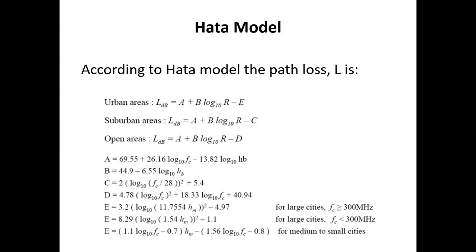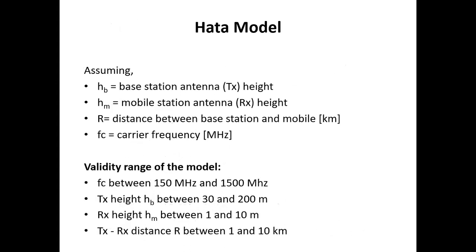But the maximum frequency was 1500 for the original Hata model, and it was found insufficient. I mean, later, for increased data rate, people added 800 bands in Asia, Europe, and 1700 band in North America. And also later, the bands around 2100 or around 2 gigahertz or 2.1 gigahertz. Okay, the frequencies were added. So people needed a little larger range. This Hata model stops at 1500 megahertz.